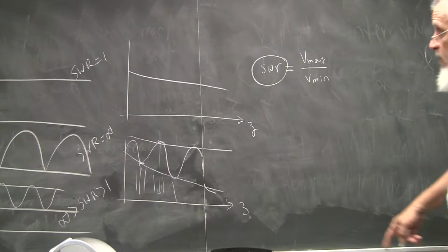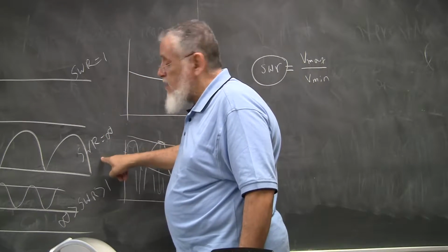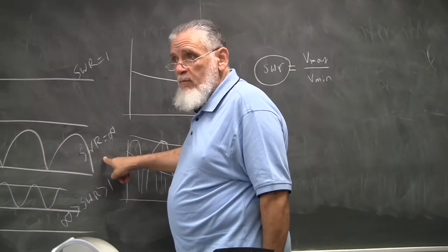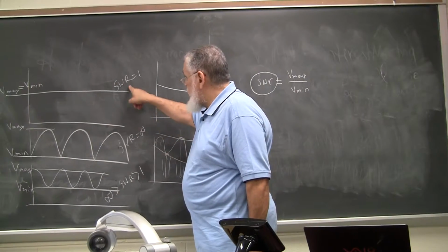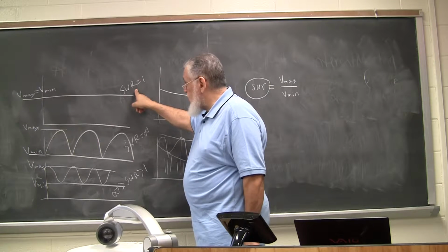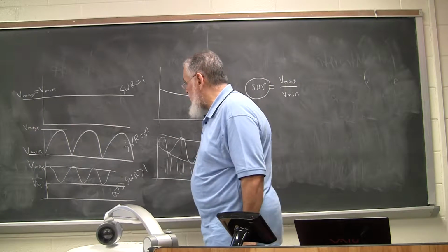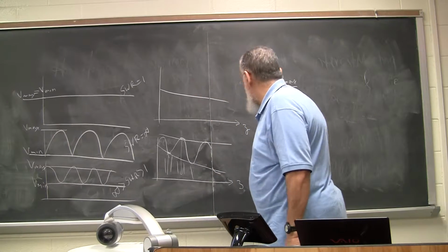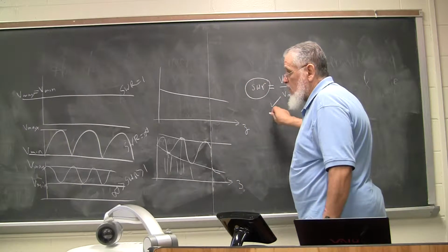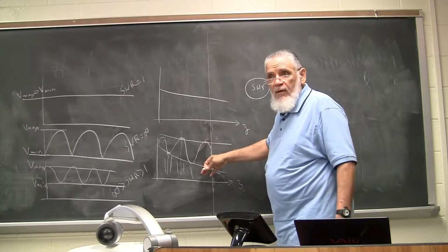So your SWR is 1.1. Oh, that's very good. We are very close to that. SWR is 20. Oh, we are too far away from the matching condition. So when the number is closer to 1, that means your device is close to matching and your traveling wave is the dominant component there. That's a typical definition here. Obviously, the real world is like this. Okay?